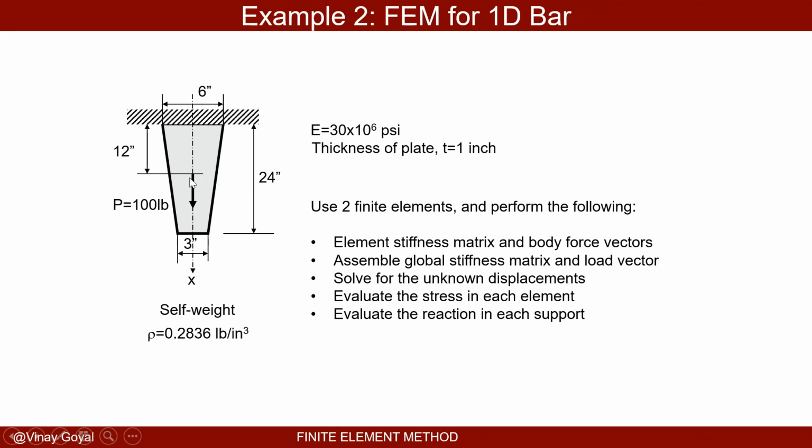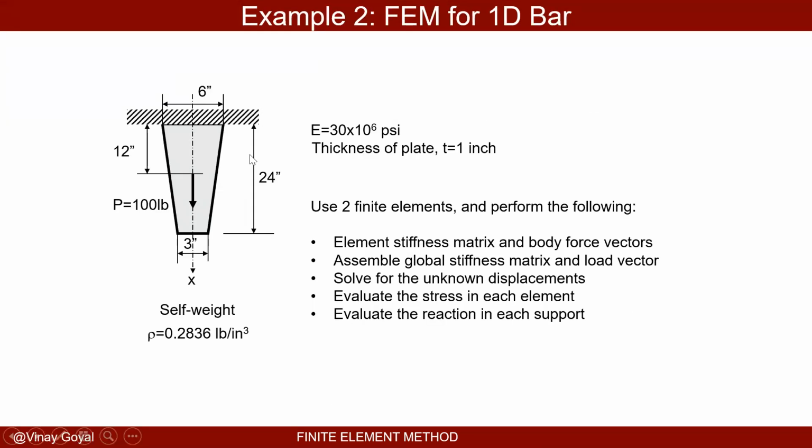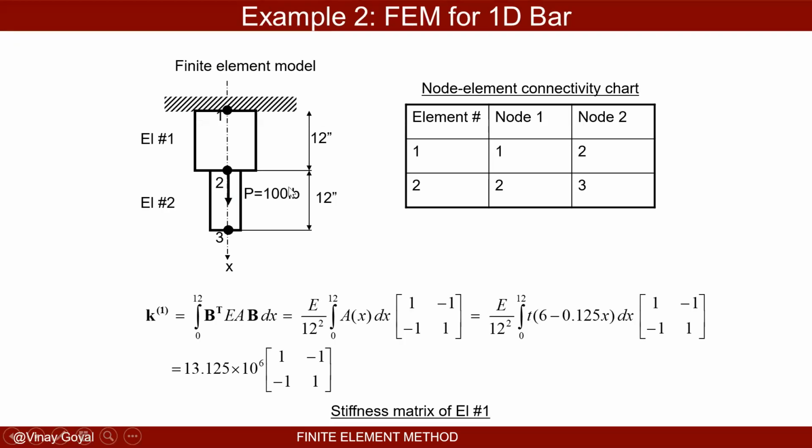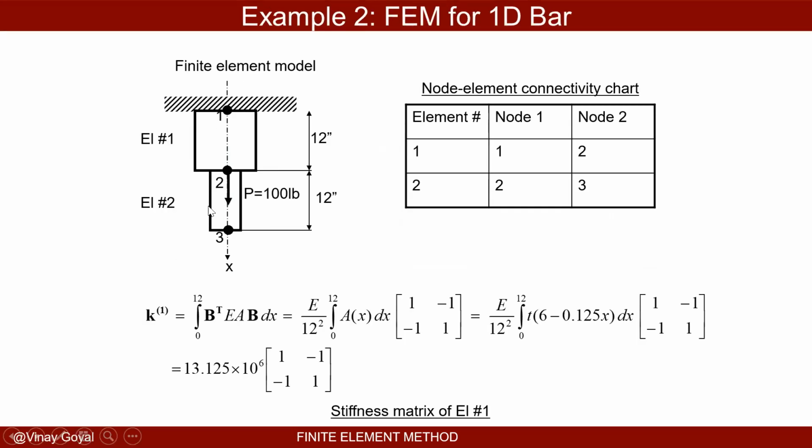And so now I go ahead and construct the finite element model for this problem. So I have two elements. I divided the domain into 2 elements, and I was sensical about how I divided the elements. Notice how I divided the elements. I did it in a very specific way. I also divided the length by 2, so 12 and 12 inch. I also have a mid load applied at 100 pounds.